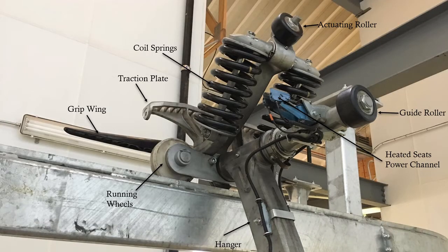Here are some important components of a detachable grip. The grip shown is a Leitner-Palma LPA single position grip. The grip wing sits on top of the haul rope when the grip is attached and smooths out the transition with depression sheave assemblies. The traction plate transmits power from rotating tires in the terminal tire banks to allow the grip to move, which it rolls on running wheels which roll along a small grooved track in the lift terminals. Coil springs provide the adequate force to keep the grip jaws locked securely onto the haul rope without slipping.